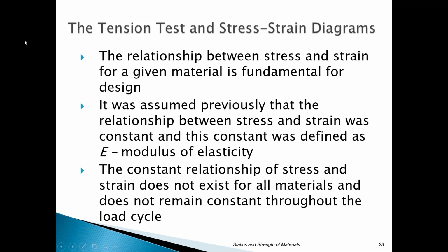Now this is getting into what we call tension testing and stress and strain diagrams. There exists a relationship between stress and strain for a given material, and that's a fundamental thing of design. As we saw, it was basically assumed in what we were just talking about that the modulus of elasticity is a constant, a linear slope of that line, essentially.